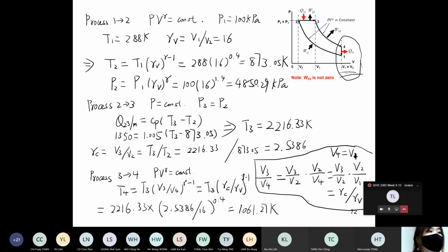Always use absolute temperature because you are dealing with air, the perfect gas. For the pressure, I still suggest you use kPa to avoid any error. So first, change your units for temperature and pressure into K and kPa.